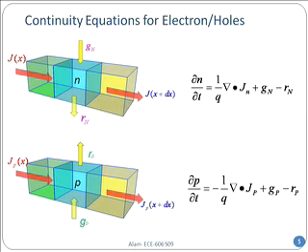And correspondingly, you will have an equation for the holes. The only thing that is different in this second equation is, do you see this? There is a negative sign in the first equation. And why is there a negative sign? Because holes carry a positive q. So when you write the equation, in the denominator you will write a plus q. And once you do everything else, because of that plus q in that term, you will have a correspondingly negative of the divergence. That's it. And so therefore, these two equations will be globally linked.